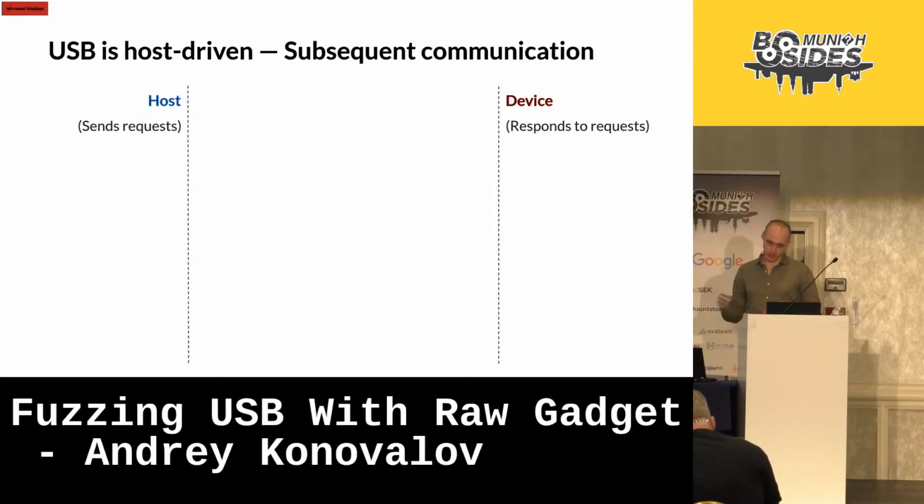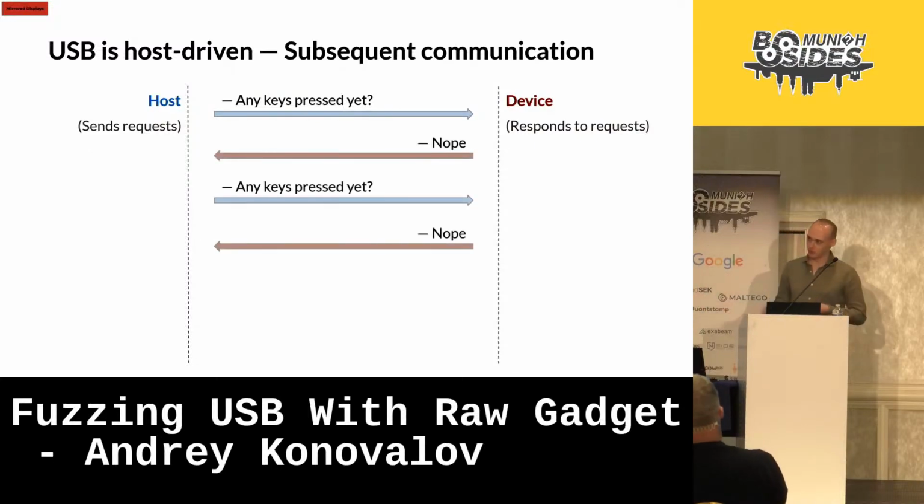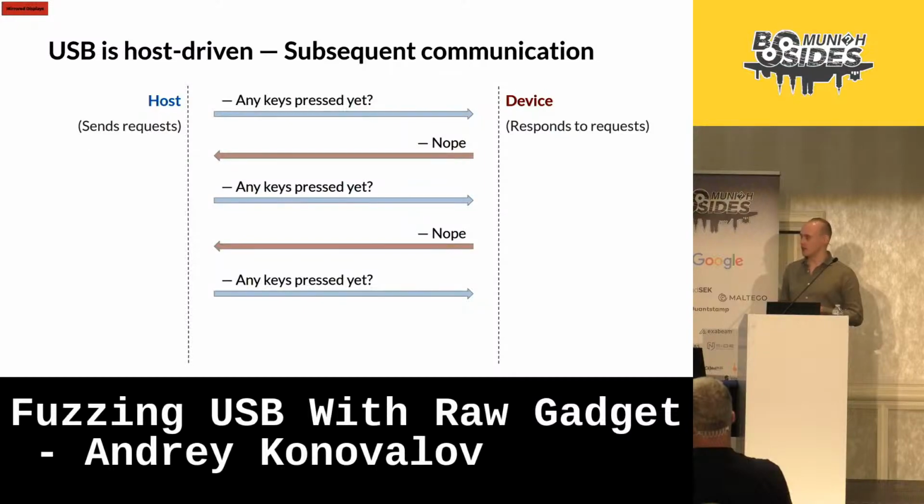And it works like this. The host just keeps asking the keyboard, which keys do you have pressed? Any keys pressed yet? The keyboard says no. Any keys pressed yet? The keyboard says no. And at some point, you press the key, and the keyboard is going to respond: now I have this particular key pressed.